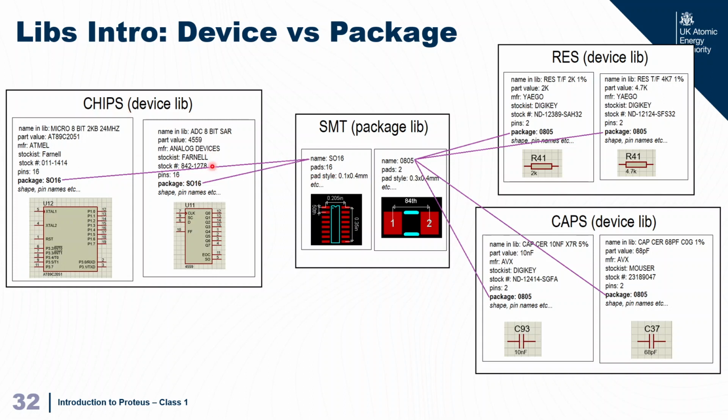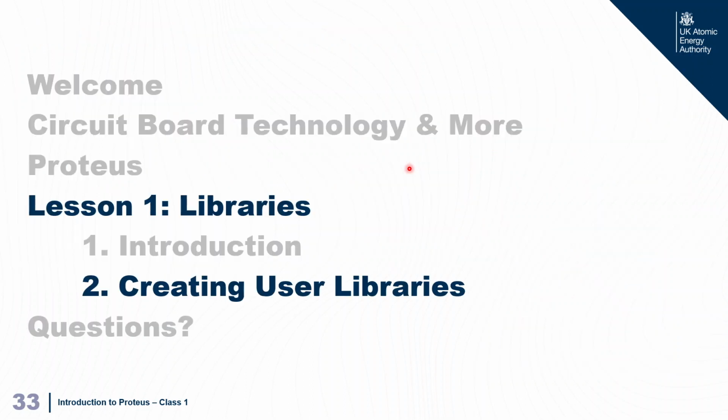This one is an ADC. It also references the SO16 footprint. These resistors and these capacitors also reference the same part. So all I'm trying to say here is that you can have many devices referencing the same footprint. And that's common because devices use the same packages.